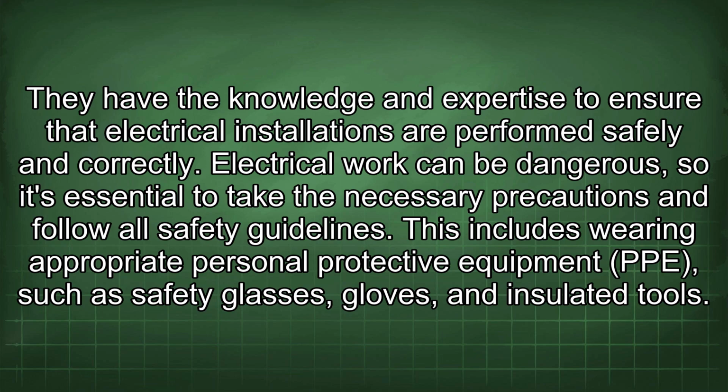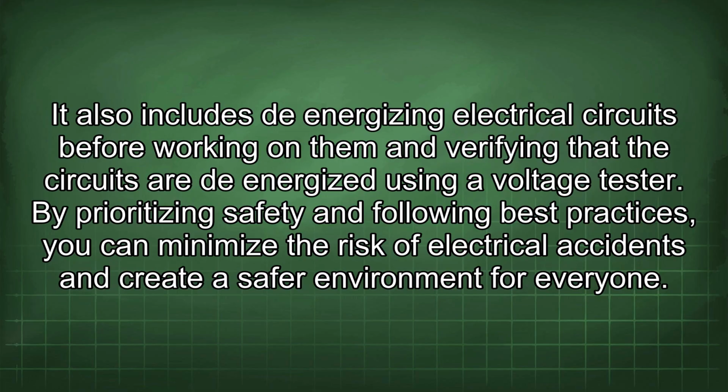Electrical work can be dangerous, so it's essential to take the necessary precautions and follow all safety guidelines. This includes wearing appropriate personal protective equipment (PPE) such as safety glasses, gloves, and insulated tools. It also includes de-energizing electrical circuits before working on them and verifying that the circuits are de-energized using a voltage tester. By prioritizing safety and following best practices, you can minimize the risk of electrical accidents and create a safer environment for everyone.